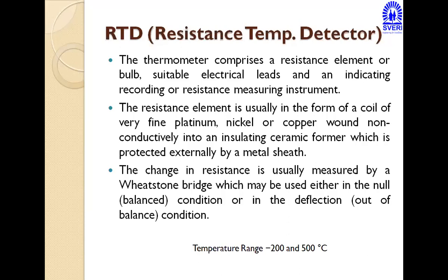The change in resistance is usually measured by a Wheatstone bridge, which may be used either in the null, in bracket balanced condition, or in the deflection, in bracket out of balance condition.